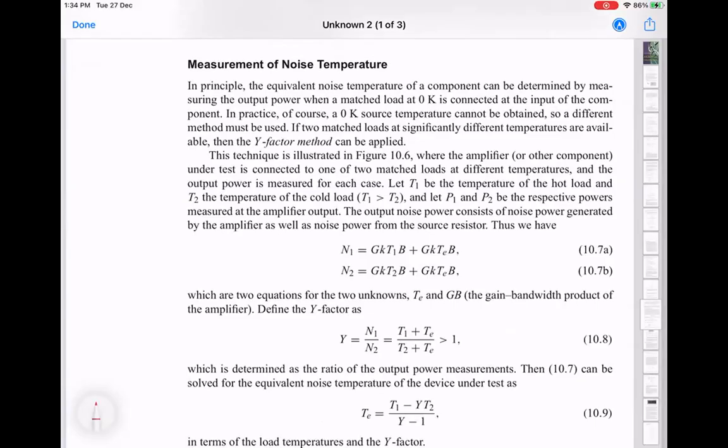Sorry? The amplifier circuit doesn't have resistance. The amplifier circuit doesn't have a resistance of 50 ohms. It should look like a 50 ohm input on both the input side and the output side.